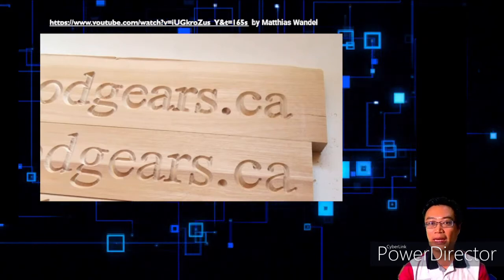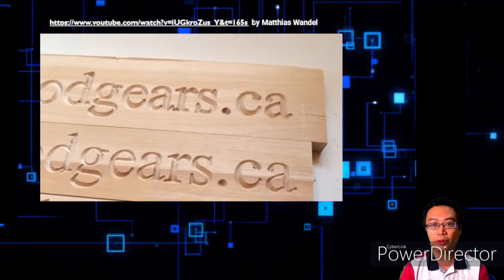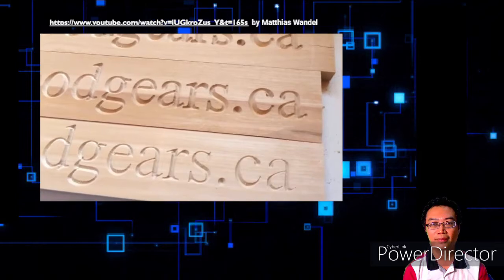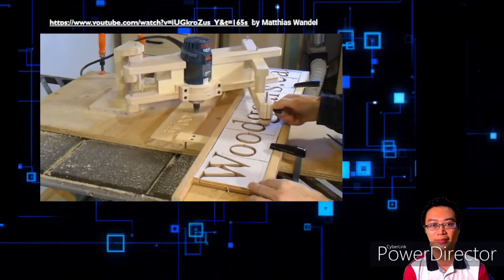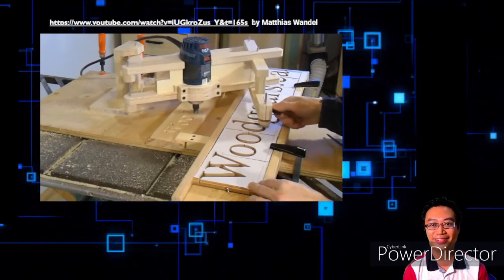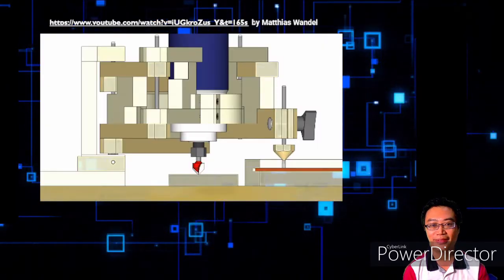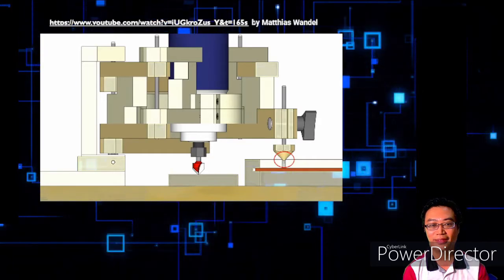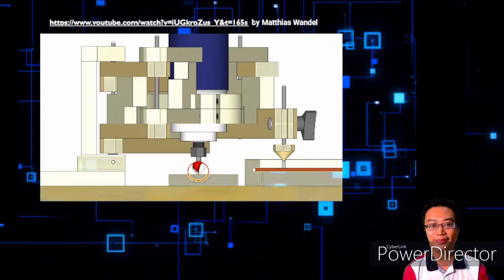Let's take a look at a pantograph used by a carpenter to carve wood. This video is about carving 3D indented letters with my router pantograph. My pantograph not only controls the position of the router but also its depth, which allows me to carve these profile letters that actually have a variable depth of cut along the whole letters. The way the pantograph works is I have a conical follower which follows the grooves in the template and a V-bit that is the same shape as my conical follower.